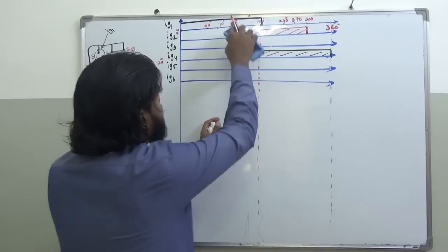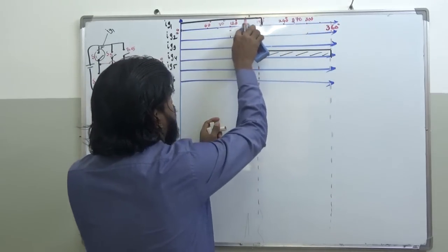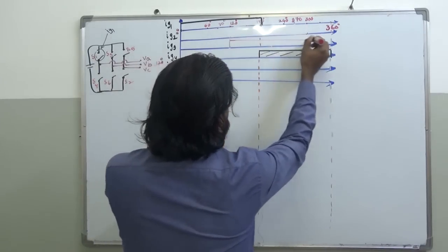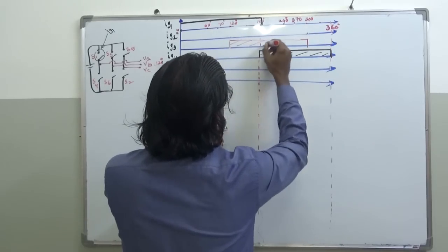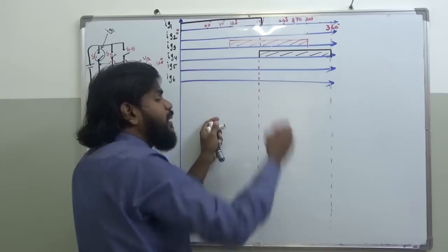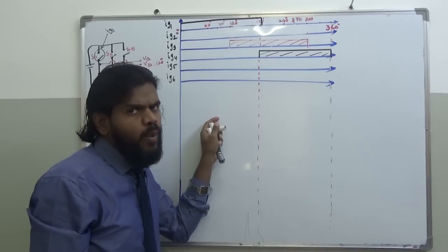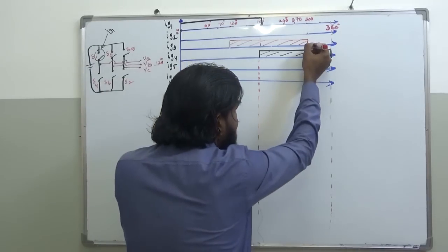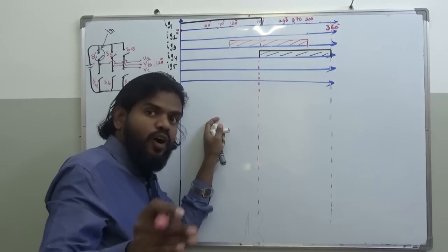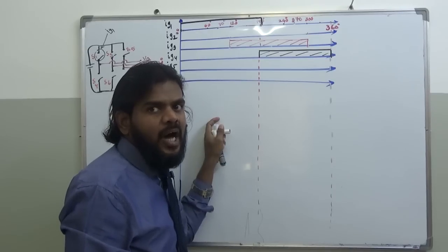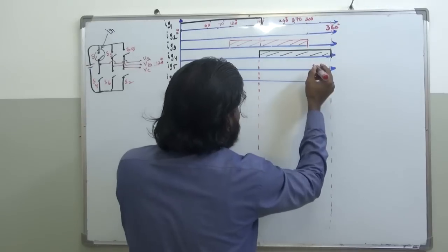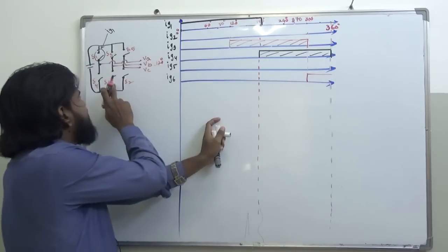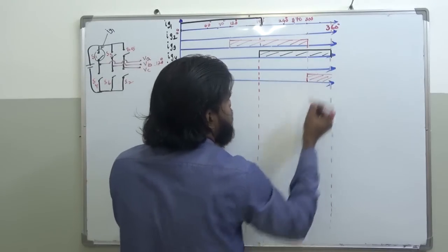So this is the gate, base current given to S3, sorry, it's not S3, it's S2. Okay, yeah, here I should give it. Yeah, this is the gate pulse which I am mentioning. So we have to give a gate pulse to the S3 switch from 120 to 300 degrees, right? And thereby your S3 will be on. But at 300, the negative half cycle of phase B is to be derived in the output. So we have to switch off this S3 and apply a gate pulse to S6, right? S6.